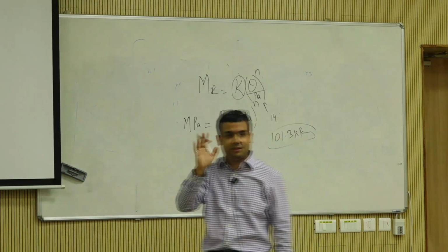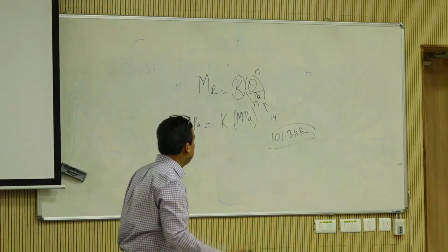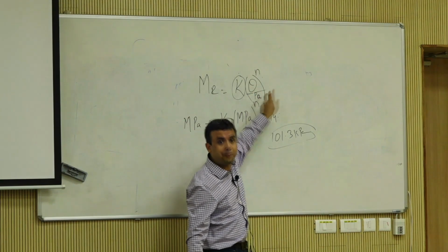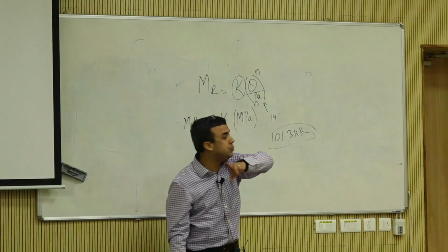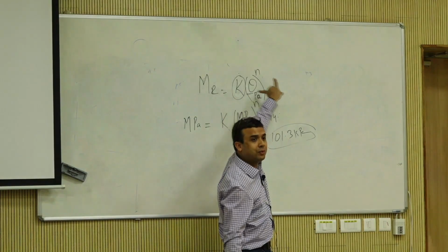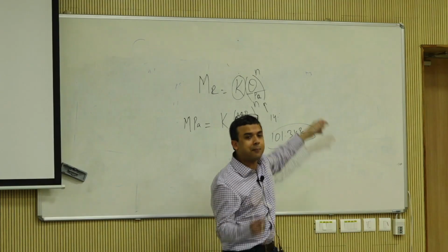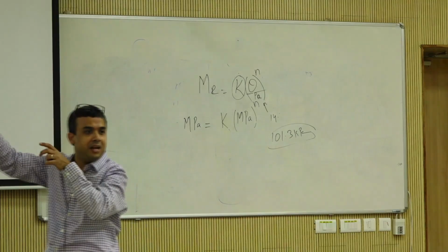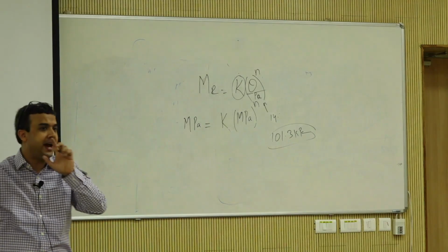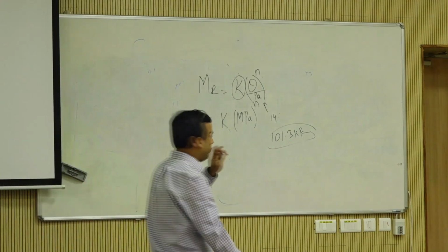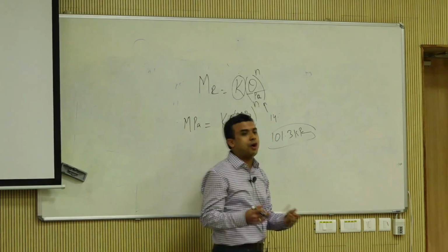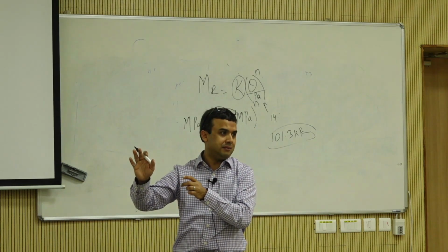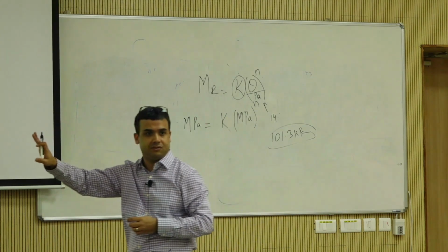But just remember that both are correct approaches. For K theta, you always do P0 because you divide by 1. Otherwise, you do realize that your model parameter values are going to change, right? Whether you divide theta by 1 or by 101 or 14.7, your model parameter values are going to change. So just pay attention to what you are trying to do. For K theta, it's more common to divide by P0, which is 1 kPa. You're just making it unitless.